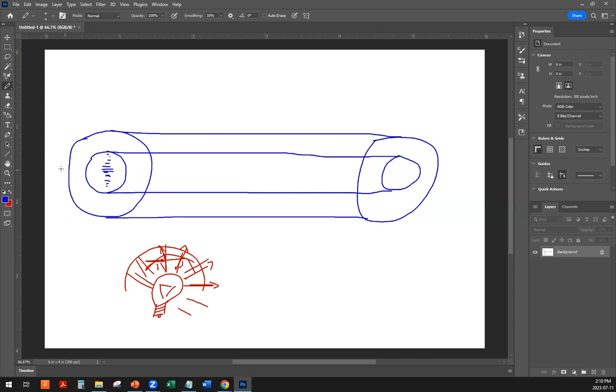Well, anything that travels in the center would have the slowest speed, but anything that travels outwards from the center, the speed of the light traveling through that would increase in this spot here compared to here. So this would be the slowest. This would be a little bit faster. And as we go outwards from the center of the core, the index is graded to be less and less. So naturally, if the index is less, the light is going to travel faster. So that would sharpen that signal so everything arrives at the same time? You got it. That's the whole thing.